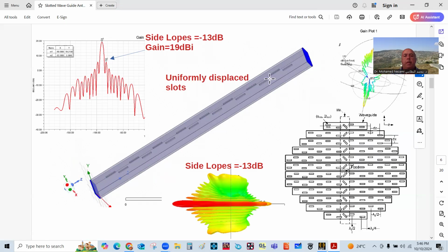And of course, now this is uniformly distributed above and below the center line of the broad wall, these slots, so that we end up with a linear array of 16 half-wave dipoles, uniformly spaced and excited uniformly. So according to the DFT or FFT or windowing technique, where it's non-windowed, you end up with a 13 dB first side lobe level, okay? And that's what we get here.